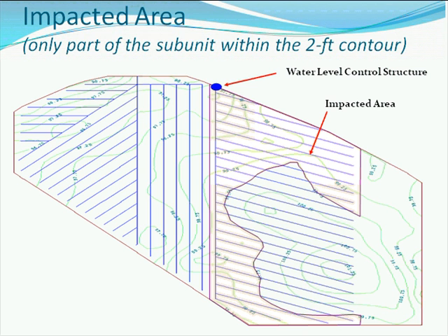To do drainage water management on that, you'd either have to put a control structure on each one of those laterals, which would be way expensive and we'd never recommend it, or you'd have to just avoid doing it at all. If you have too much rise in the drain lines above that 2 foot mark, it could lead to ponding of water at the structure and potentially even blowing it out. So we just want to be careful.